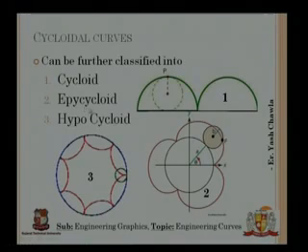Moving on to epicycloid. Instead of this line, if I make this circle with point P rotate on another circle on the exterior side, as shown in figure number 2, this is a circle with point P rotating on the exterior of this circle, then this point traces this red path which will be named epicycloid.